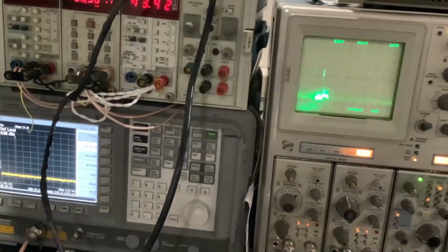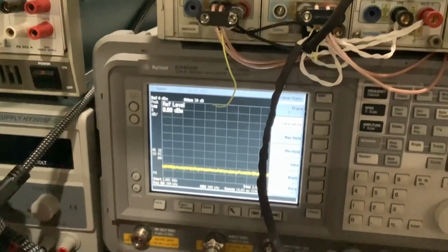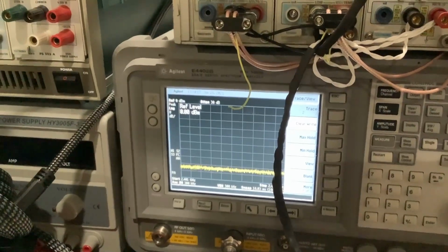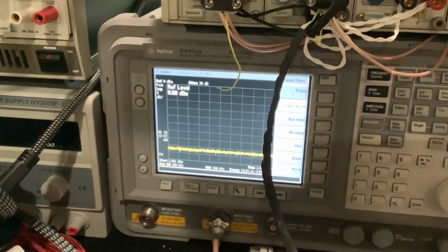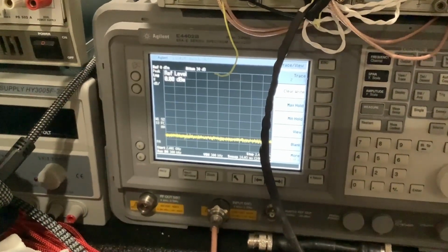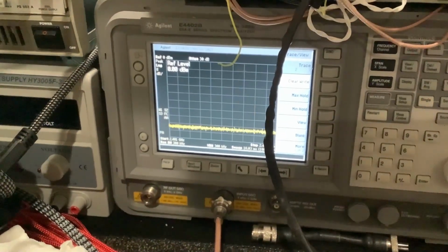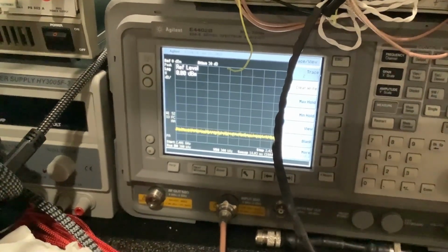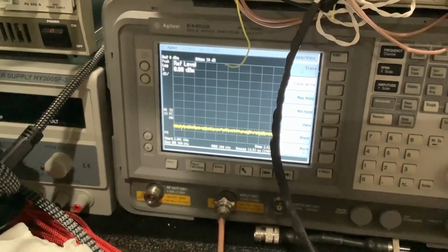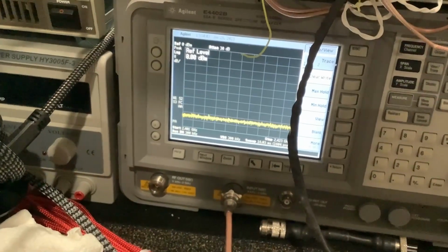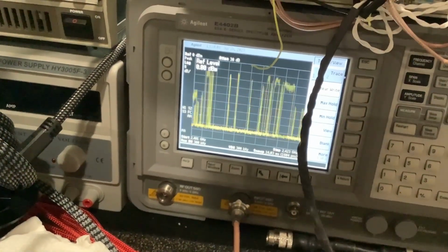So why is this important to audio? Well, this RF that's coming out of here in this bursty manner, audio gear is not going to receive this 2 gigahertz signal. But what it could do is induce a DC voltage or lower frequency currents as it saturates these interconnects and these circuits that weren't designed for this 2 gigahertz signal. So it could modulate what's going on in the gear and on the signals by this low frequency bursty rate.